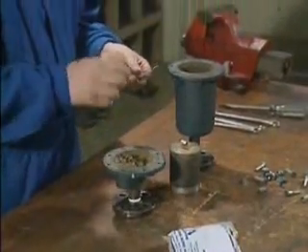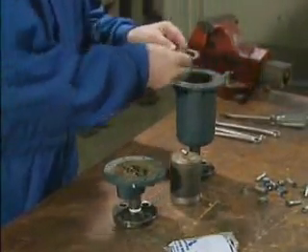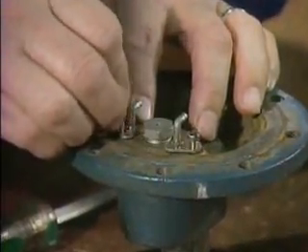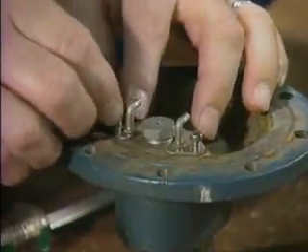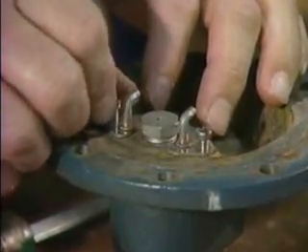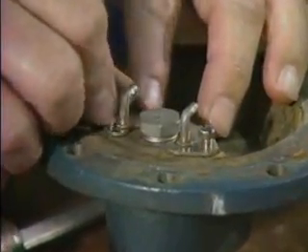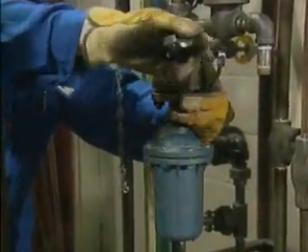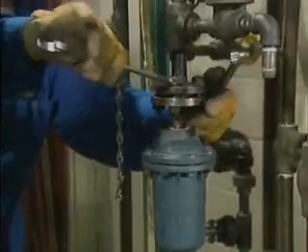Now, install the required replacement parts, including a new gasket. Because manufacturers usually sell the valve and the seat as a single assembly, you should replace both the valve and the seat whenever either one of these parts is damaged. Finally, follow your facility's procedures to install the repaired trap and bring it back online.